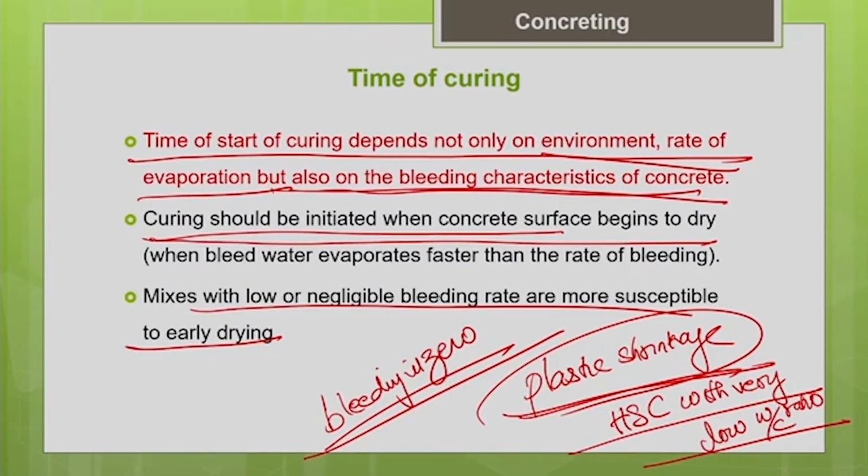If your mix composition is such that it has very low water to cement ratio, in those mixes the bleeding will be negligible. Very cohesive mixes with low water to cement ratio, the bleeding will be negligible, so the concrete will dry faster. That is why to protect those mixes, you have to start the curing as early as possible. We cannot wait till finishing. You need to start your curing even before finishing of the concrete.